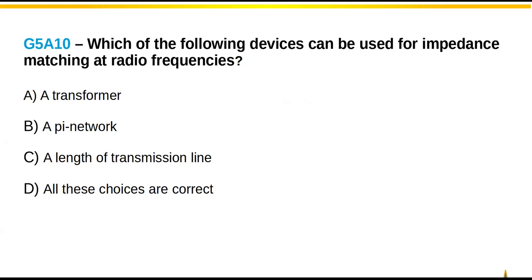You can calculate the temperature rise, knowing the mass, and calculate how much energy it takes to raise that. Would you see at that point with a pure resistive element as a load, where we're not radiating and having to capture the RF, but just turning it into heat that we can measure, are we going to measure 50 watts of thermal power dissipated by that dummy load, or are we going to measure 100 watts of thermal power?